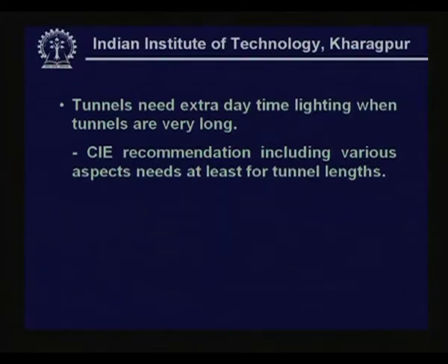CIE recommendations consider this depending on the tunnel length. If the tunnel length is less than 25 meters, no daytime lighting is required.